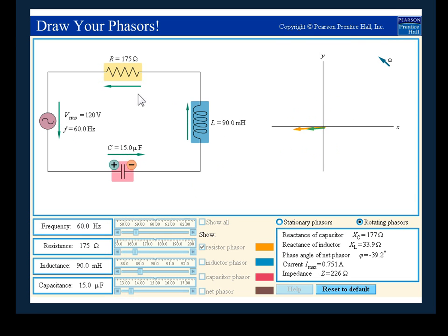It also goes up and down with a progressive change in the direction of the current, and one can understand that behavior in the phasor diagram itself by looking at the projection of the current as shown by the green arrow. So right now it hits zero, the projection is negative maximum, here it's positive maximum, it's zero, negative maximum, positive maximum, and so on.